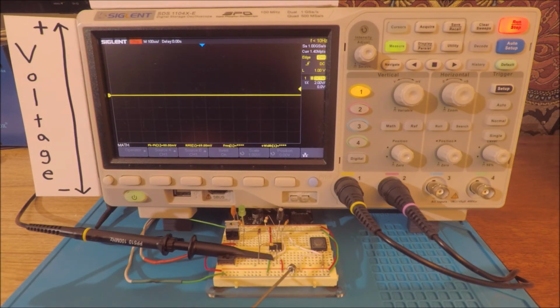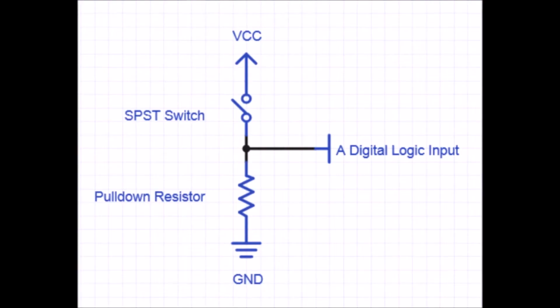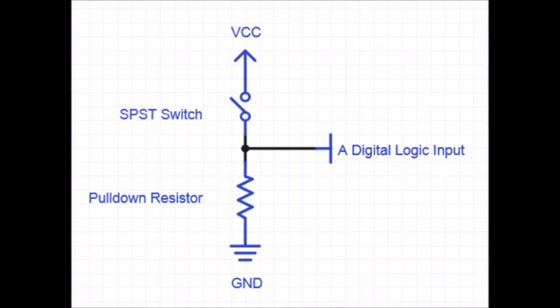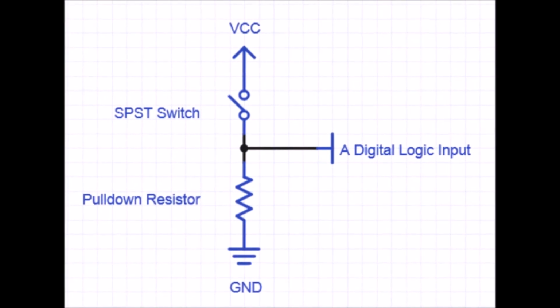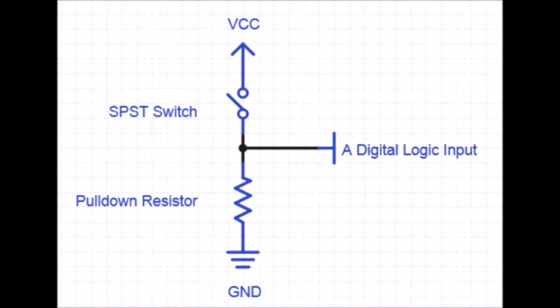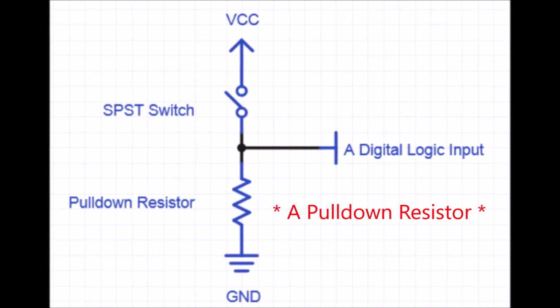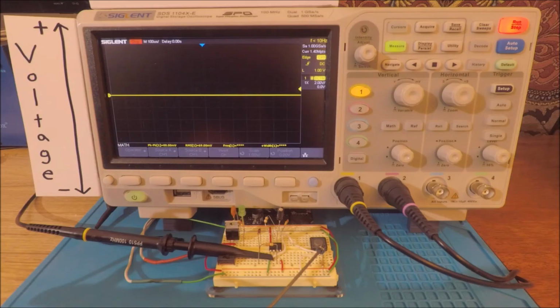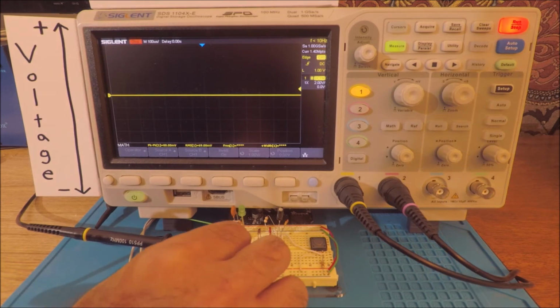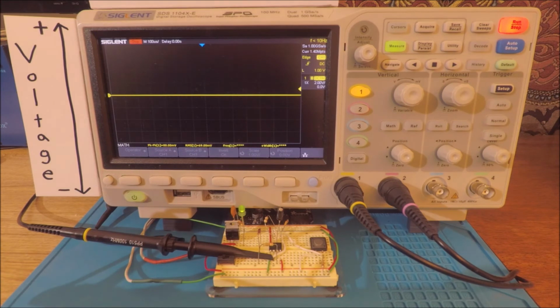On the breadboard here, I have a small circuit where we have a momentary push button switch, which is connected to 5 volts through a pull-up resistor and then ground on the other side. So the 5 volts are being supplied by a 7805 regulator right here. I can turn on that regulator with the slide switch. And we have a little indicator LED that comes on right here.